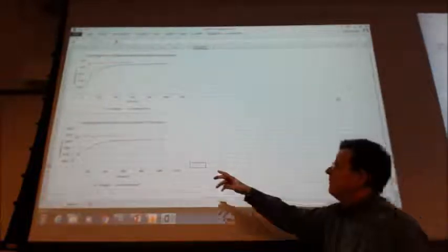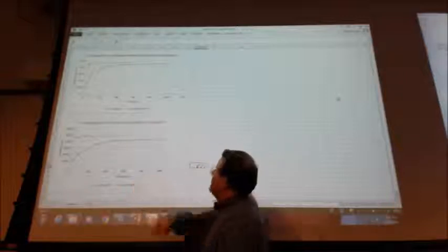Back here at less than 200 elements, I've pretty much converged, where it takes over 800 on triangles to get out to the right value. Stress, same thing, first or second iteration.